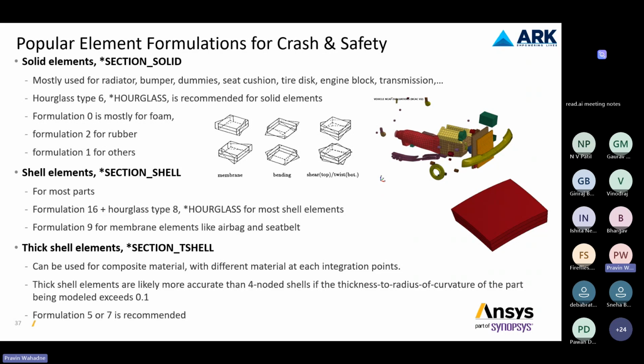But in most of the cases for other elements also, we can use *HOURGLASS as a card, where it minimizes the hourglass effect. Hourglass is generally a kind of zero mode energy which is developed within the elements, which will show you high deformation without any stresses developed in it. It will be just a change in the shape of the elements, and it will take the shape of an hourglass.